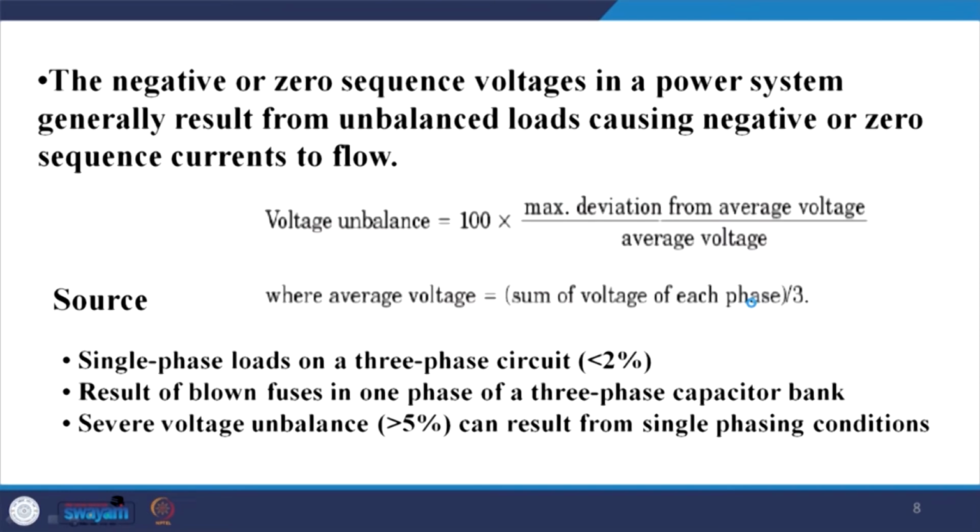So, another is the negative sequence due to the unbalance. The negative or zero sequence is present only in a 3-phase 4-wire system in a distribution network, otherwise zero sequence is absent. We shall discuss in detail the zero sequence and negative sequence components in the shunt active power filter. You can refer back to those lectures once they have been delivered to you.